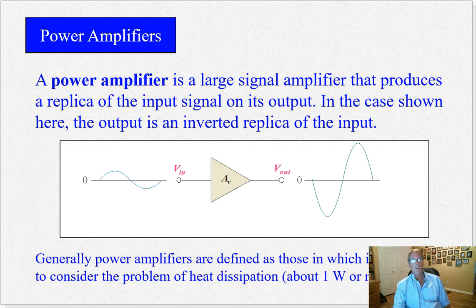So in this case, we have an amplifier that has an inverted transfer function, so the input rises and the output falls. And this would be typical of a common emitter amplifier that we talked about last time. A common collector amplifier, however, an emitter follower, you would not have this inversion happening, remember. It's a voltage follower. We'll look at both topologies in this chapter as well.